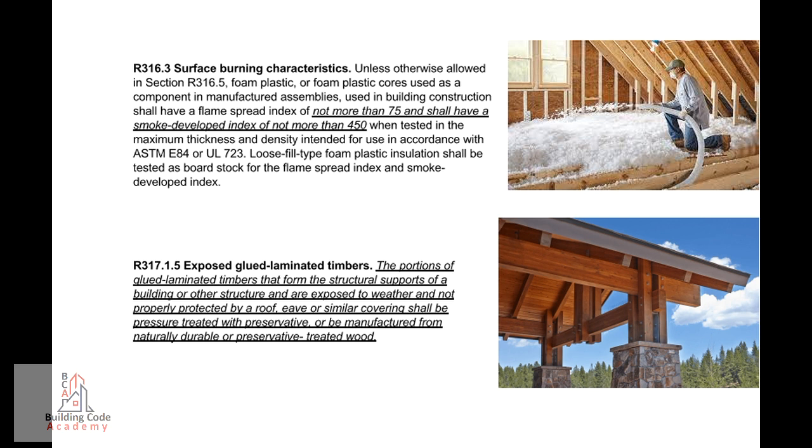R317.3.2 Fastenings for wood foundations. Fastenings, including nuts and washers for wood foundations, shall be as required in AWC PWF, American Wood Council and Permanent Wood Foundation. R317.1.5 Exposed glued laminated timbers. The portions of glued laminated timbers that form the structural supports of a building or other structure and are exposed to weather and not properly protected by a roof, eave, or similar covering shall be pressure treated with preservative or be manufactured from naturally durable preservative treated wood.